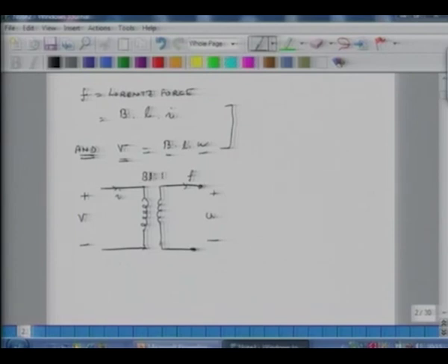So I can on this side put all sorts of inductors and capacitors and resistors, and I can have as complex an electrical circuit as I want. And on this side I can have whatever number of mechanical elements there are in the real system. And if I have to compute force, if I introduce this particular coupling element, then I am able to convert voltage into velocity and current into force for mobility analogs.